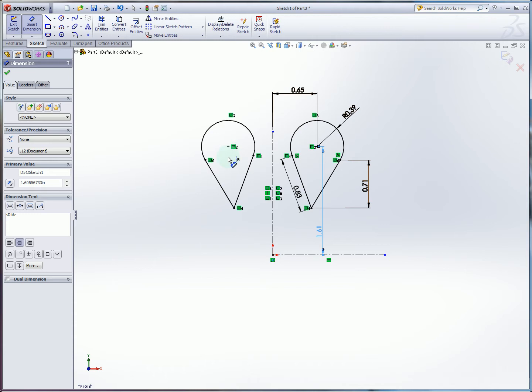In general, this is a principle you want to try and follow: keep the amount of sketch features that you have to control minimal. The fewer lines and dimensions and such you have to draw, the easier it's going to be to get right, and the fewer errors you'll introduce through general human error.